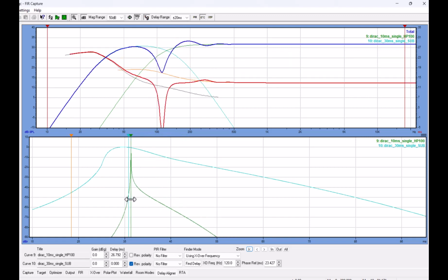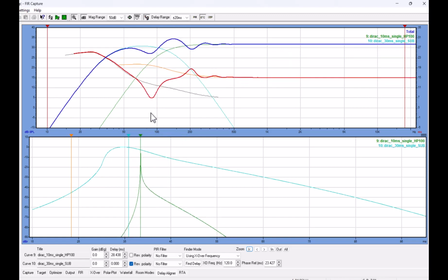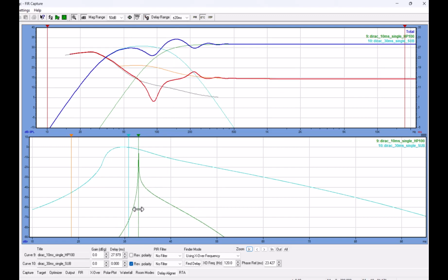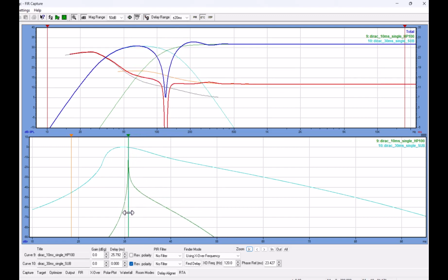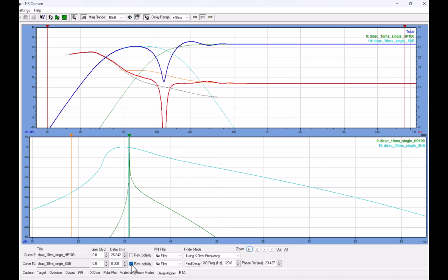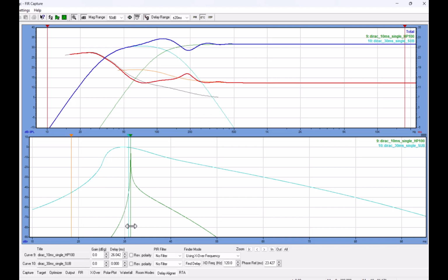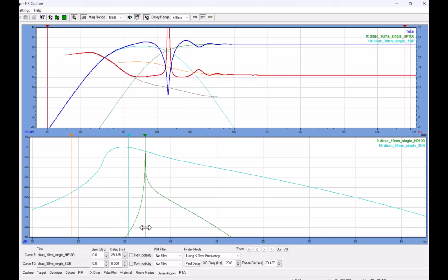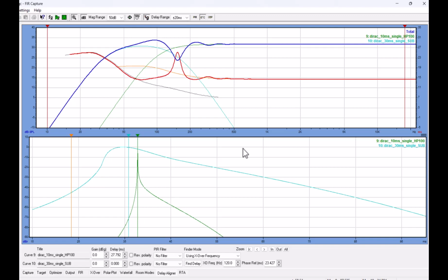But of course, if you trim the top system, you get something like a fake linear phase system at the crossover region, but it still will be two different minimum phase systems, because a linear phase system should have constant group delay.